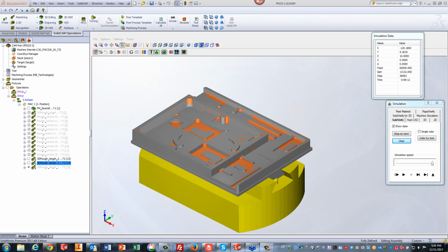Okay, now one more thing I would like to mention is that a couple of weeks ago, in the webinars, we had a problem with the drivers for the NVIDIA card crashing, and I had mentioned to update your drivers. Now, the very newest NVIDIA driver is actually not the best one that should be used. There's another one instead, which is recommended by SolidWorks itself. The driver is release 311.5. If you go onto the SolidWorks site, you'll be able to see it there as well. That is the correct one to use. So if you're having problems with your NVIDIA card crashing on your SolidWorks, just redo the driver to the one I had just mentioned.